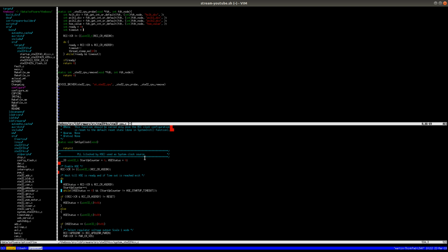I will use 50 milliseconds. I don't want the system to just be paused for 1 second if for any reason it doesn't start the HSE.